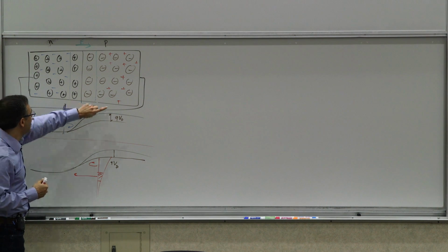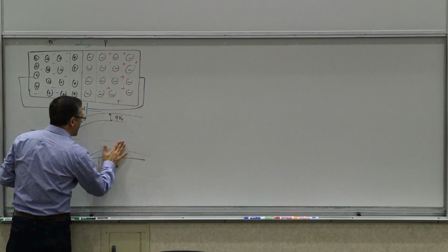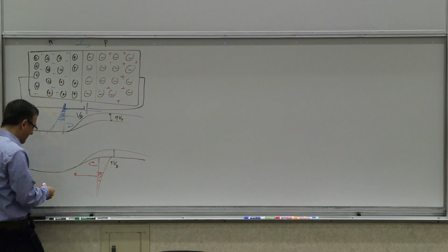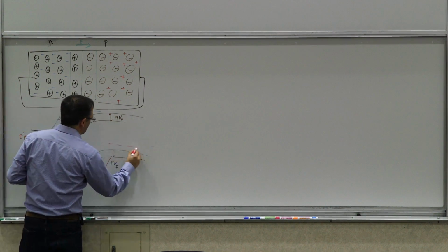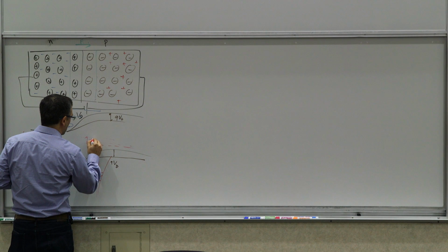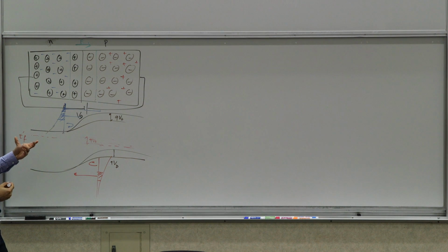And now this current may be a constant DC current. But it does not make the system in thermal equilibrium anymore. So basically you will not have a constant Fermi level across this thing. It's meaningless to define that, because the Fermi-Dirac distribution is meaningful only in thermal equilibrium. Now you are in steady state, but you're not in thermal equilibrium. And what sometimes people do is define quasi-Fermi levels. That there's a local Fermi level here and a local Fermi level there, and they're different. And the difference is, of course, qVD. So that's the picture that we developed last time.